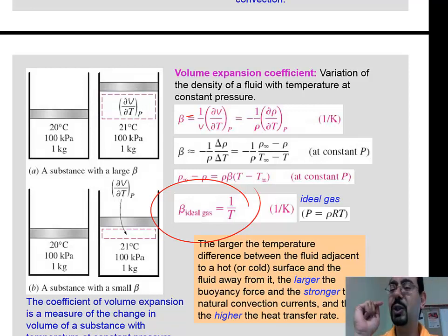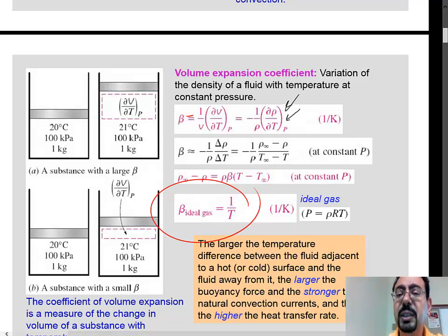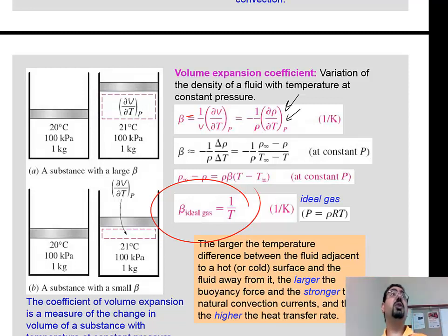So I would encourage you to actually learn how this equation came about, because in simple cases, you can actually prove why the heat transfer is a function of the Rayleigh number. But the main motivator we said was the fact that you get lighter, or basically this, partial rho, partial T. So certain fluids, their density will change a lot when the temperature gets changed.